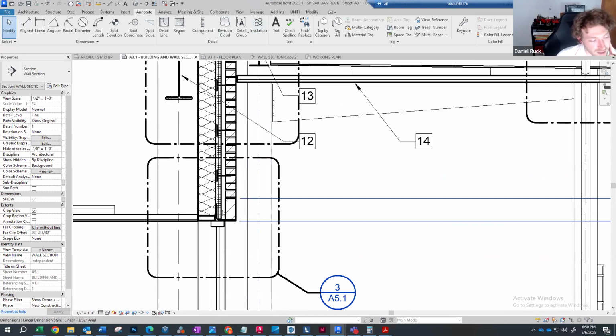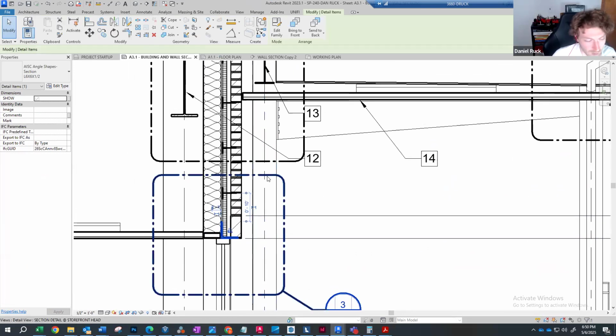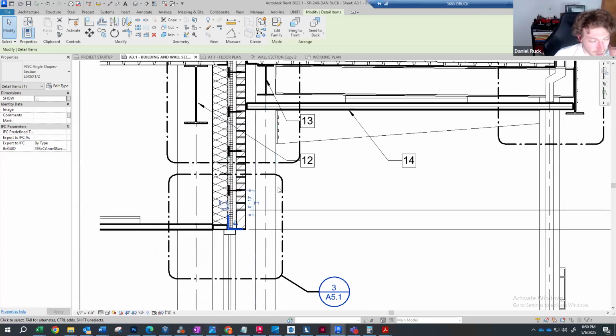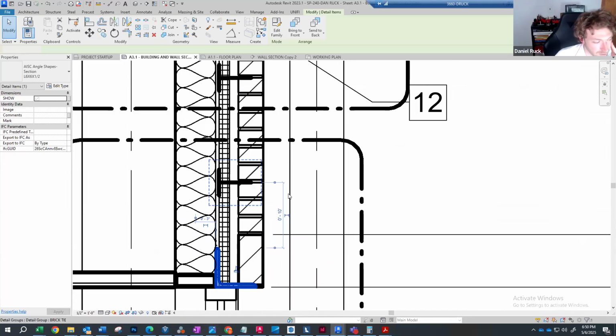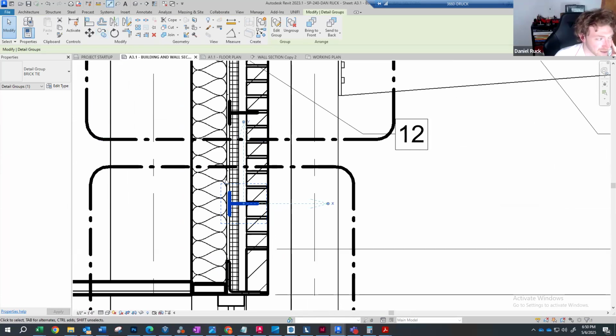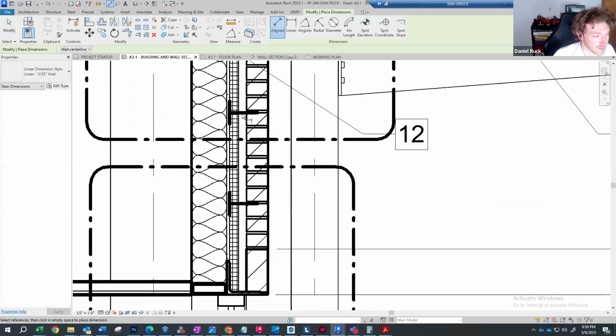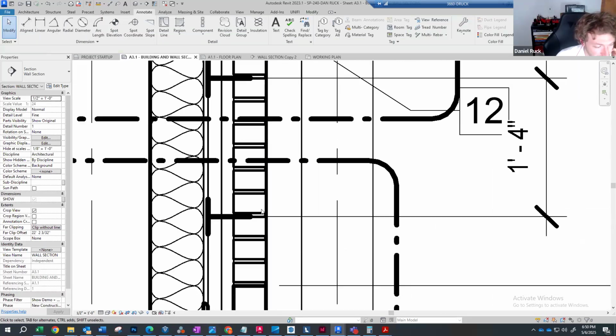The brick needs something in addition to just the angle support to be structurally sound as part of your wall assembly. What is typically used is called masonry ties or brick ties. Graphically, it is these elements here that are spaced 16 inches on center, and they are located at the grout joints of the brick.